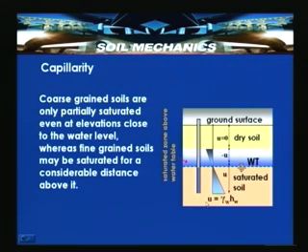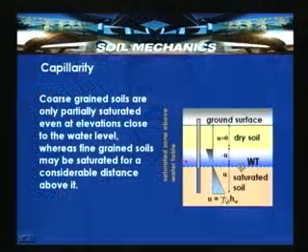The pore water pressure can have this particular distribution, because the water which rose above the water table, above the zero or atmospheric pressure, can be called negative pressure. The water column drawn and kept within the pore space against gravity above the water table is said to be in tension, and the water below, in hydrostatic conditions where no flow is occurring, is under compression.